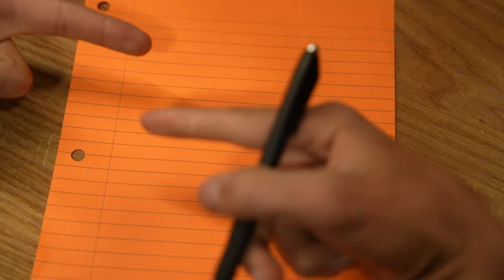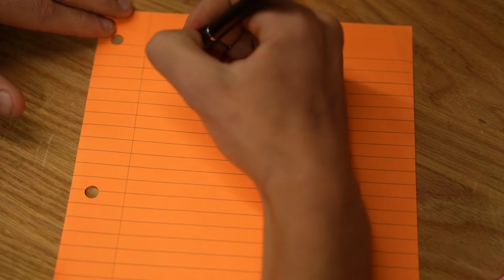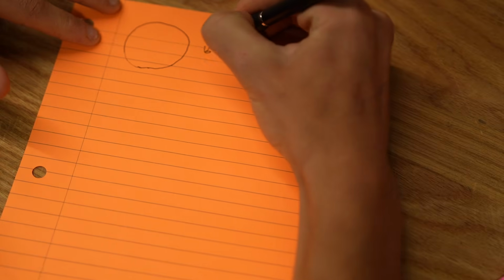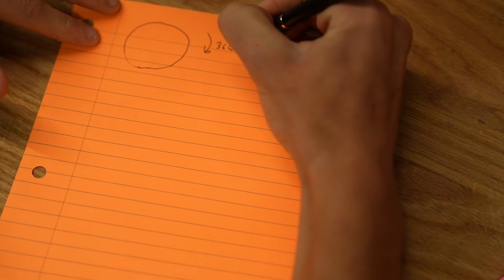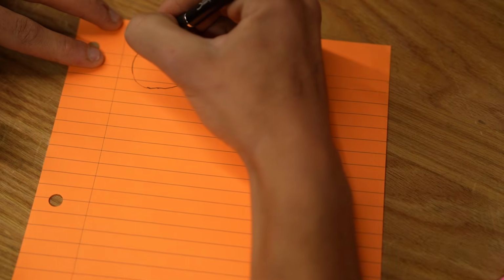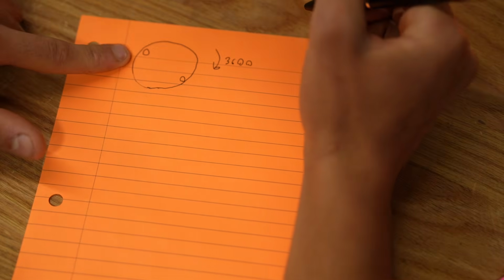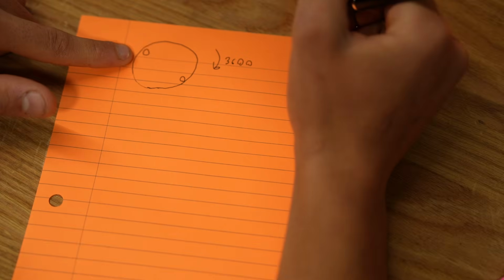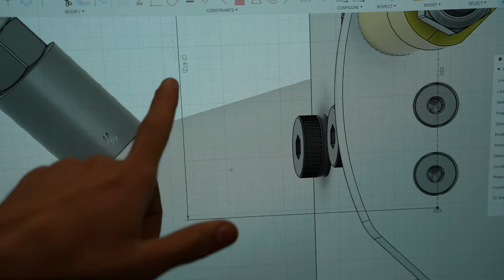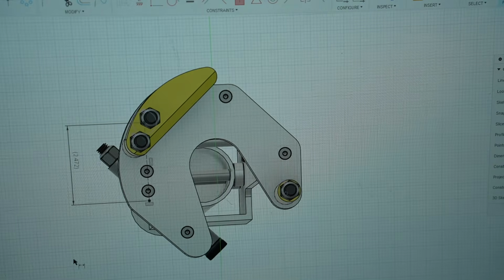So let's get to analyzing. The first thing we want to do is establish how big the forces on the nub and hook are as we try to resist our 3,600 pound load. Right? So we have one nub here, and the bolt that touches the tower of our hook there. Those have a center distance of, so it's going to be 2.47.